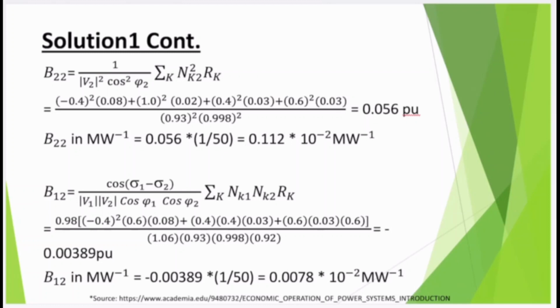Once you get those values, you can take different load profiles of the same network and average it out, and then you can confidently create an empirical formula saying that the losses will be X coefficient times P1 square, Y coefficient times P1 P2, Z coefficient times P2 square. All right, so then you can perhaps do it.